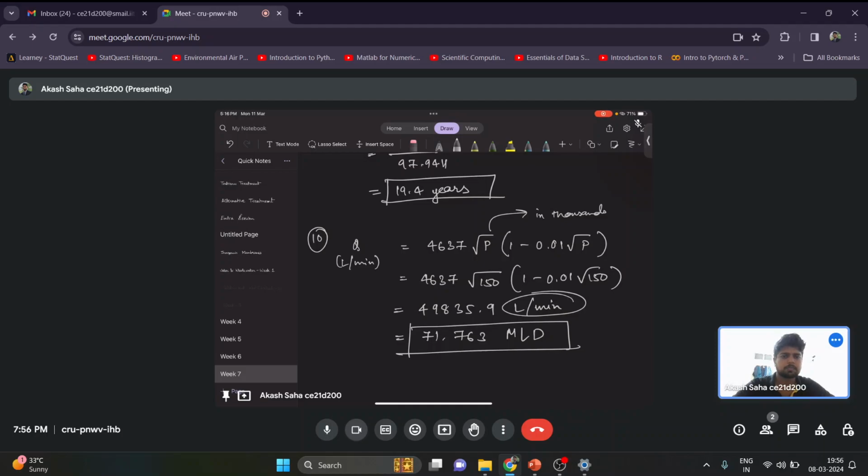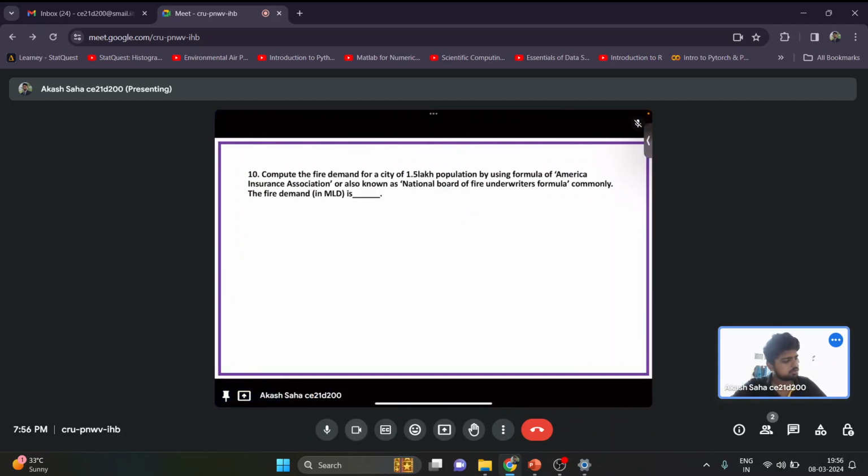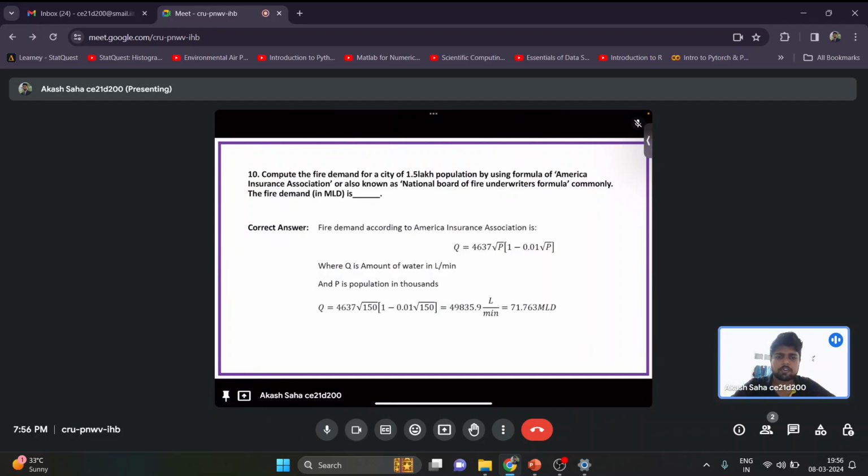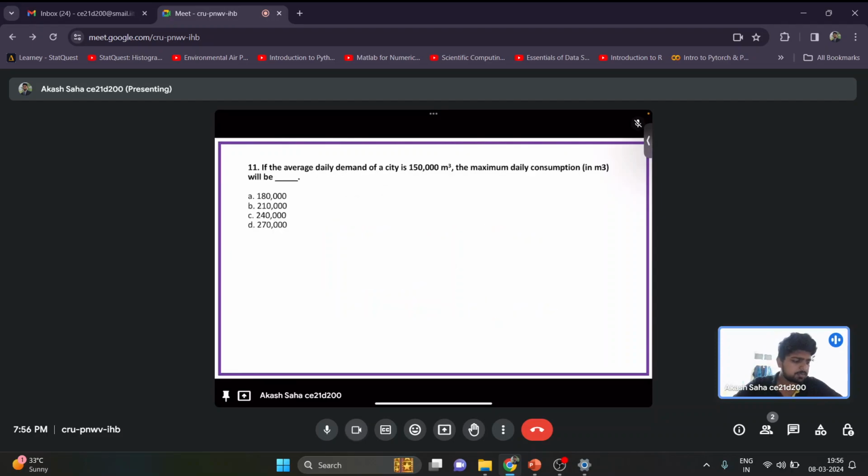Okay. So I hope it's clear. It's a very easy and direct question. So this is the answer: 71.76, around 72 MLD will come. Just make sure that you are putting P in thousands, that is the population in thousands, and the final answer is in liter per minute. Okay, so next problem.